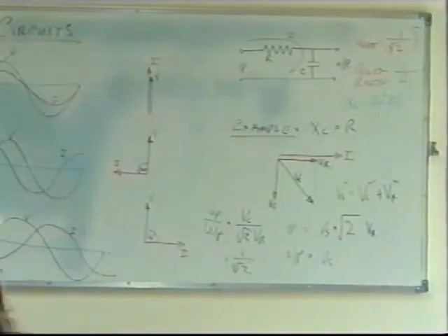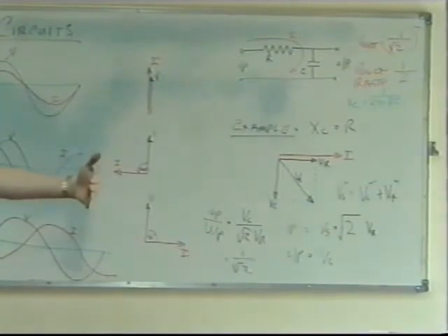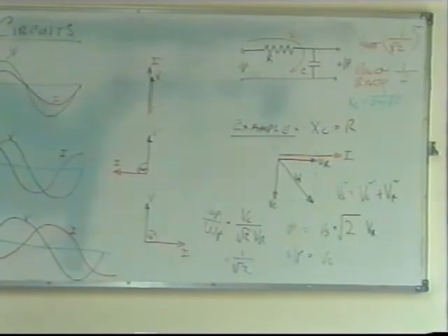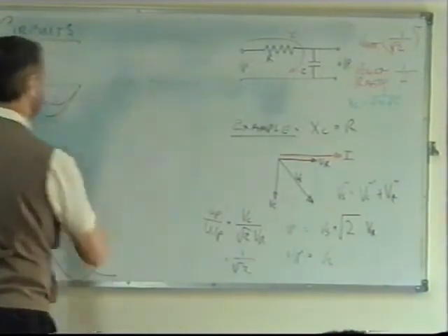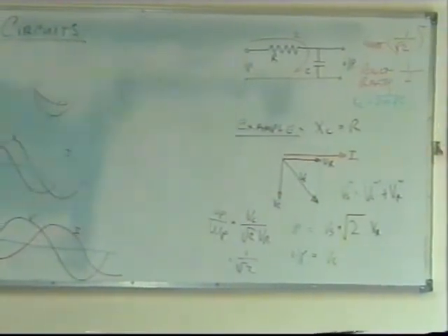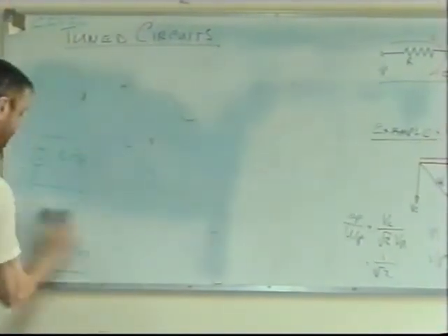If you remember your decibels, what does half power mean? It is attenuation, so it's a negative number. Remember, multiplied by 2 is 3 dBs, so dividing by 2 is minus 3 dBs. So we call that frequency the half power frequency or the minus 3 dB frequency. Now let me just erase this and put the results of this on this side.